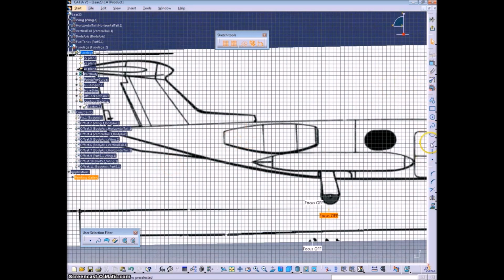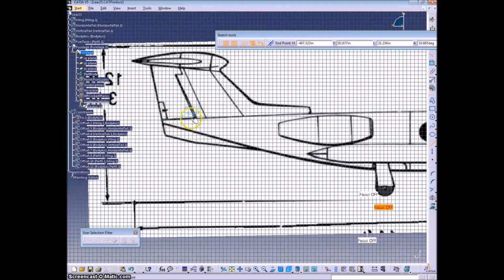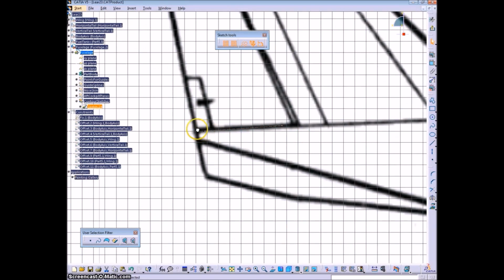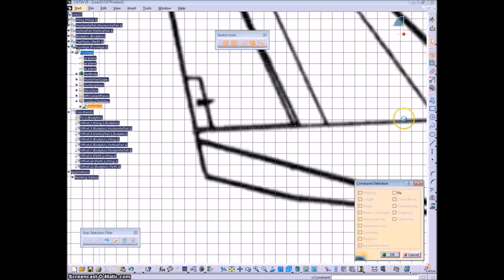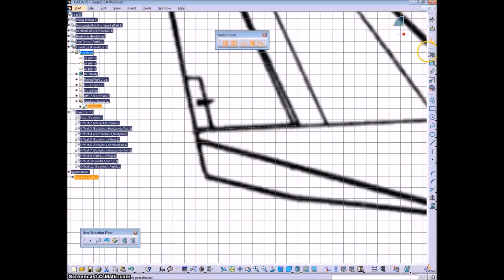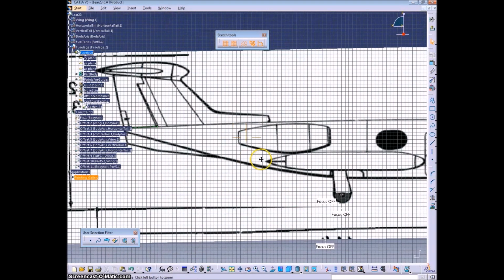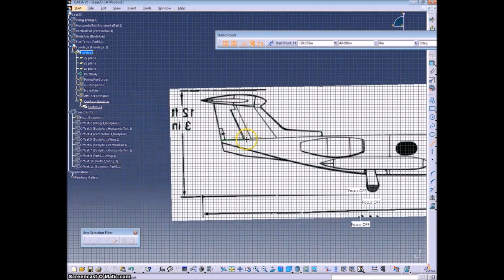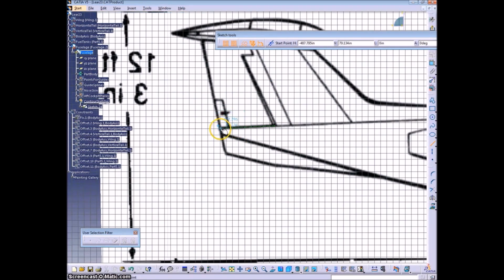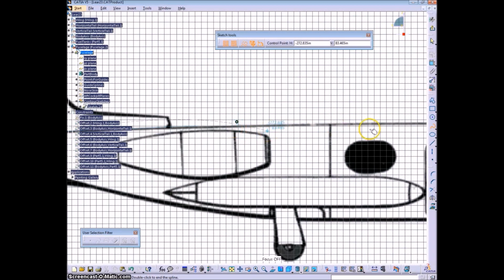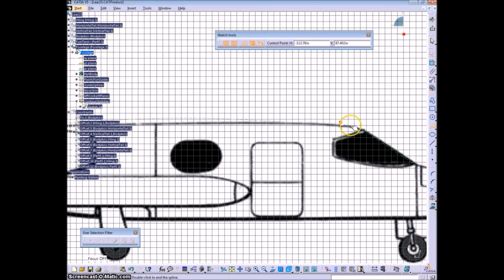And I'm going to add another line on the aft section of the fuselage here. We'll just pretend it's a fairly good approximation to assume that that's a linear slope. Okay, and then we'll add a spline going from the back point up to the windscreen. Just throw in a couple of points, maybe four to seven, somewhere in there.